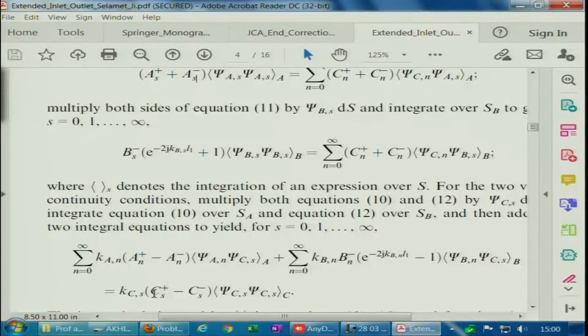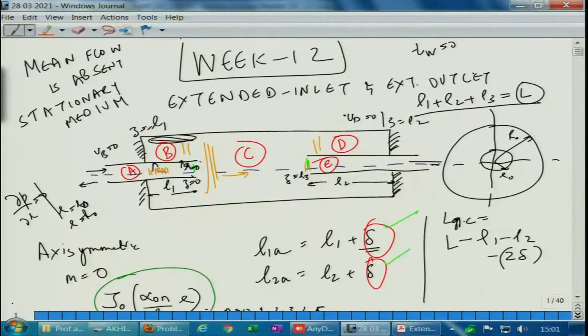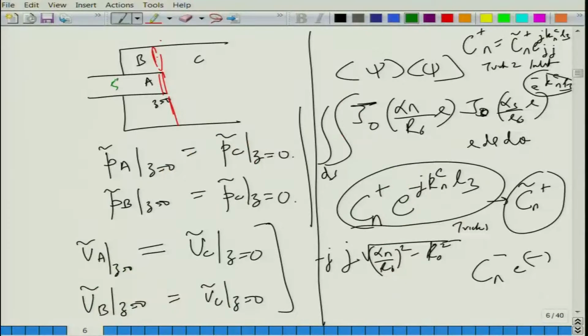We can have different numbers of constants in the chamber, in the port, and different numbers of modal summation values n in the inlet port, as well as in the cavity here or in the chamber. So, basically, what I mean is that if you go to the presentation, in this thing we can consider, say, first 5 modes here, 10 modes here, 20 modes here, or actually 10 modes here, same, this would not be too different, or you can have 10 modes here, 10, 10, 10, basically n1 modes here, n2 modes here, n3 here.